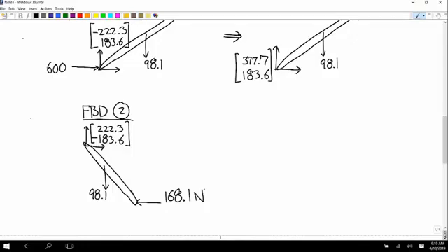And so now if you wanted to, for the people who are taking deform or who've done mechanics and materials type stuff before, if you wanted to figure out something about stresses and strains inside there, now that you've calculated those forces, you can just ignore the accelerations and just do the beam analysis on this member now. Assuming, like, now you can just assume that it's a statics problem.